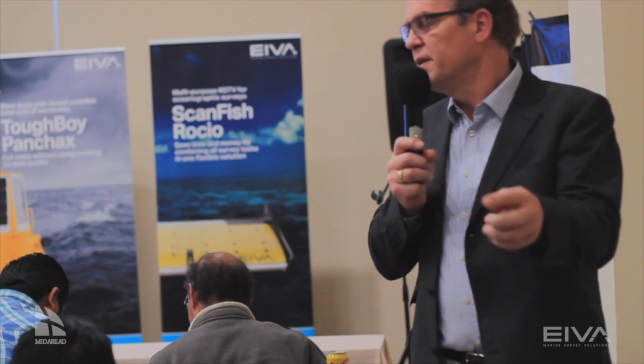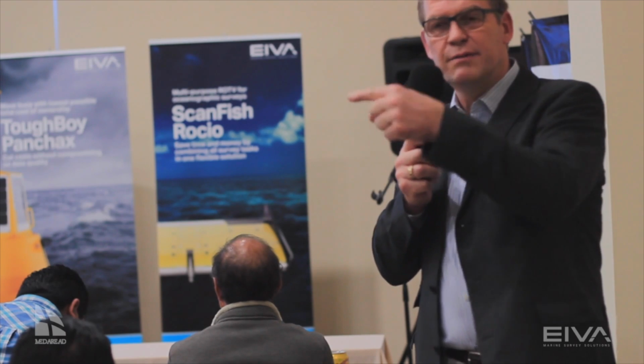Because of the delay on that? Yeah, we know. But normally you use one PPS signal from the GPS to synchronize all the sensors. Or we even have another possibility, a box which we distribute, where you can input all the sensors. They are time-tagged in this box. That's a Linux-based PC. And then only one Ethernet cable runs to the survey PC and gives you each interval time-tagged directly to the survey PC.